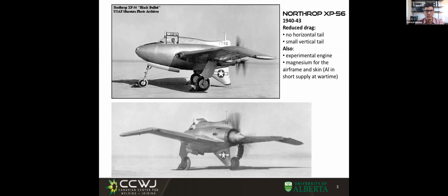Typically in TIG, the electrode is negative, which means when this is negative, the electrons will be jumping out of it. And because tungsten is a thermionic material, it's convenient, and it has some advantages. When we study the physics, we are going to see that this makes a lot of sense.